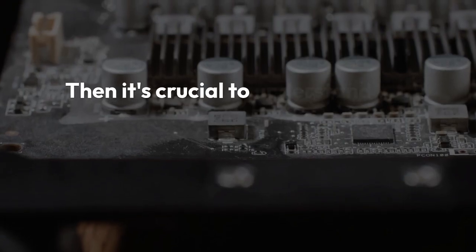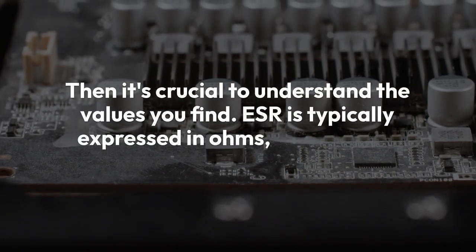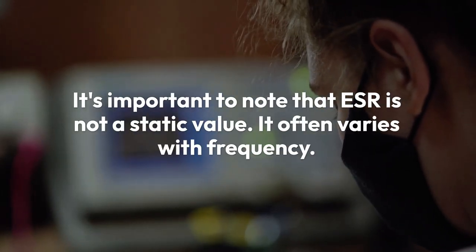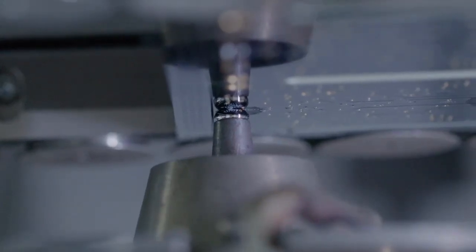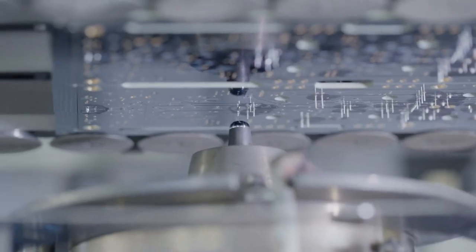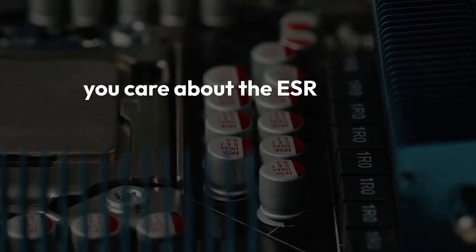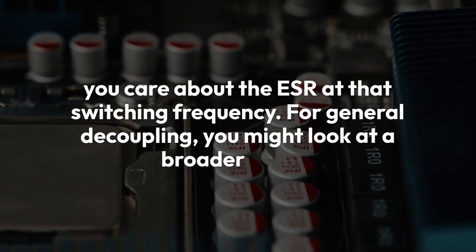Then, it's crucial to understand the values you find. ESR is typically expressed in ohms (Ω). It's important to note that ESR is not a static value. It often varies with frequency. The datasheet might include a graph showing ESR versus frequency. You need to find the ESR at the specific frequency your circuit will operate at. For example, if you're designing a high-frequency switching power supply, you'll care about the ESR at that switching frequency. For general decoupling, you might look at a broader range.